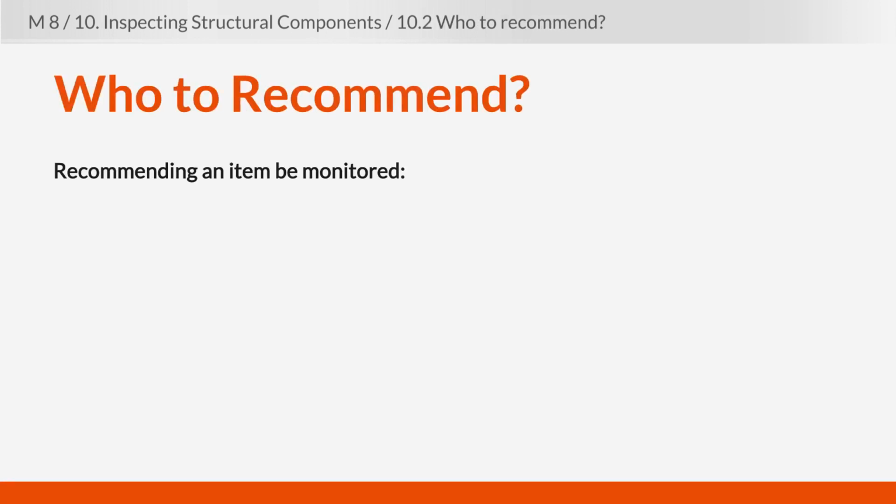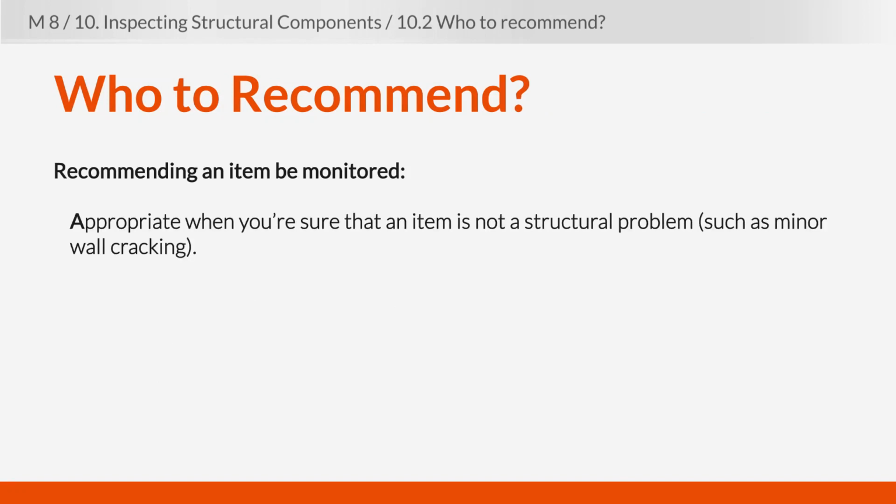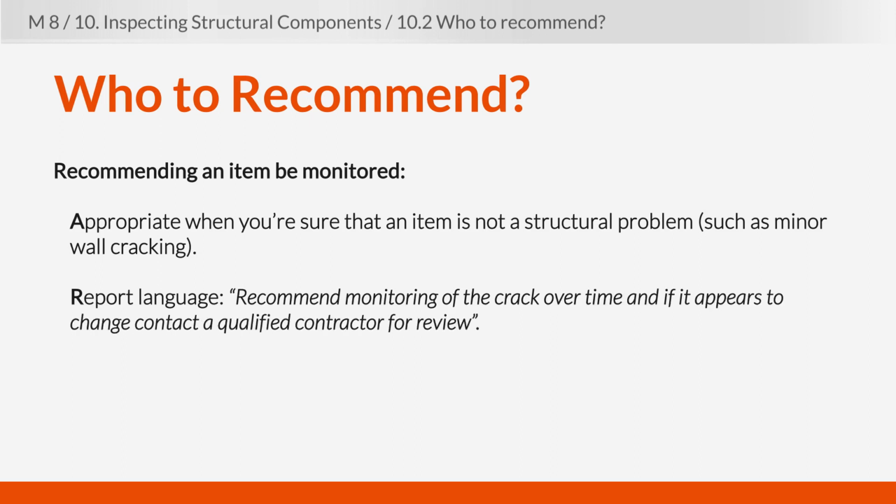So, recommending that an item be monitored by your client is appropriate when you're sure that an item is not a structural problem, such as minor wall cracking. What you would say in your report is that you recommend monitoring of the crack over time. And if it appears to change, contact a qualified contractor for review.